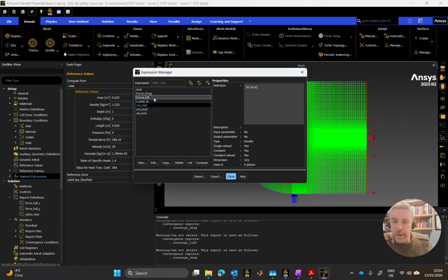So we'll have that there. Now let's go on ahead and calculate our coefficients. When we have a drag force, all we need to do is divide that by the area, which would have been taken from our reference values. So again, in 2D, it's just going to be our chord length, a chord length in meters, but don't forget it's area, so that's meters squared, by our density value as well, multiplied by 1/2 our velocity squared. Right, so let's try that.